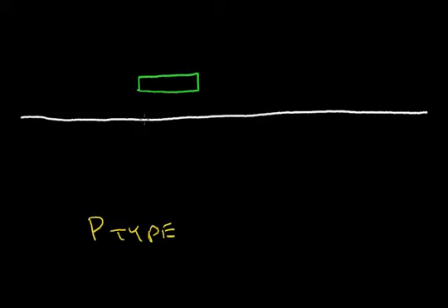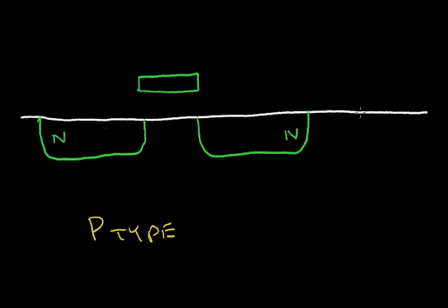So let's look at the structure of the MOSFET transistor on a silicon wafer. This is the surface of the wafer. Let's say it's a p-type wafer, so this is p-type. And I have a gate electrode I'll show here. And there's a source and drain diffusion, and I'll use an N channel, so this will be an N region. The green here is an N-type region, N-type, this is N-type. And to make contact to the p-type substrate, there will be a p diffusion in here.